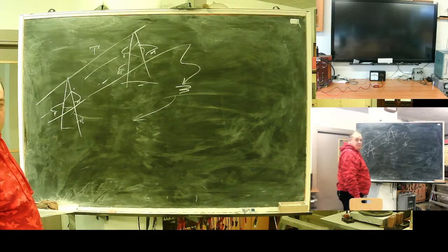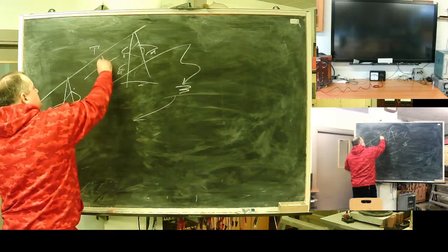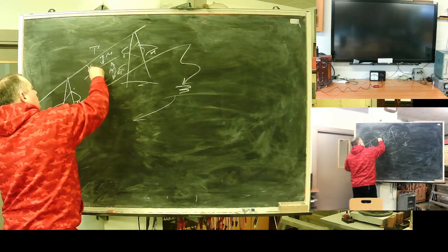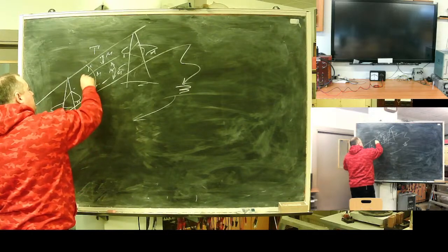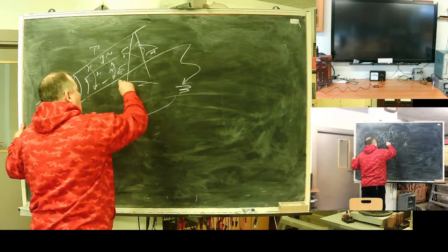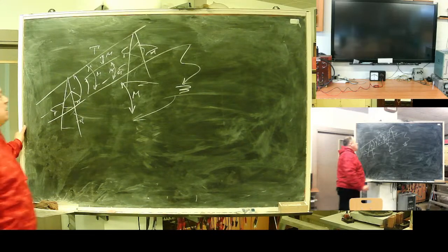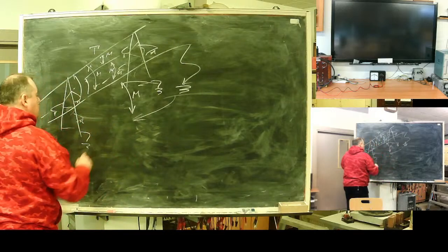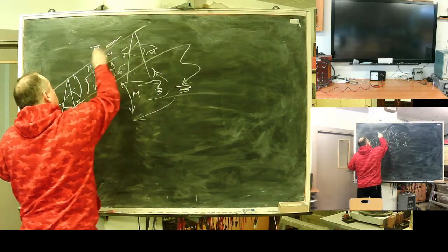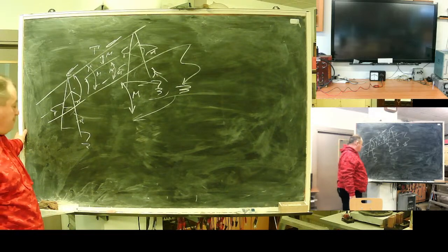And what kind of problem do I face? For each wire, there are magnetic couplings between wires, between wires and the protective wire, and also magnetic coupling to the ground current. Towers are earthed, and sometimes it will happen, sometimes not, that part of the current will flow through the protective wire.